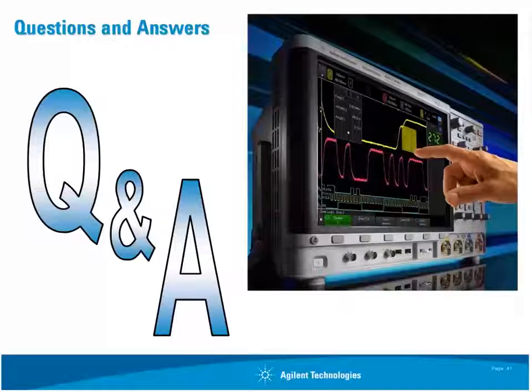Also a question, how is it possible to achieve 1 million waveforms per second if the scope display is updated just at 60 hertz? Well, that's a good question. Most scopes today have a flat panel LCD type display, and they have a refresh rate typically of 60 hertz, so they refresh approximately every 17 milliseconds.